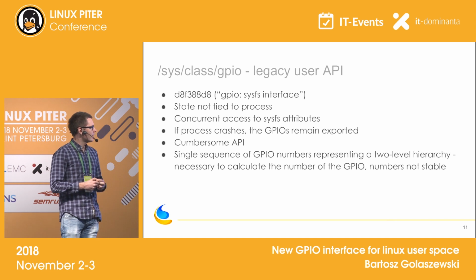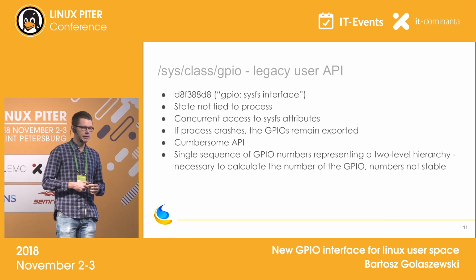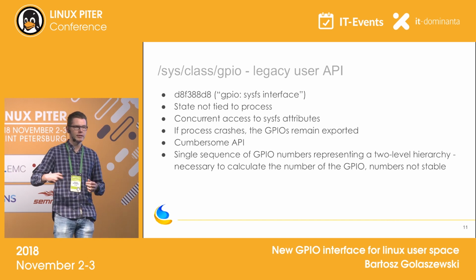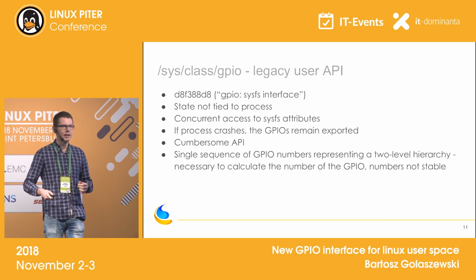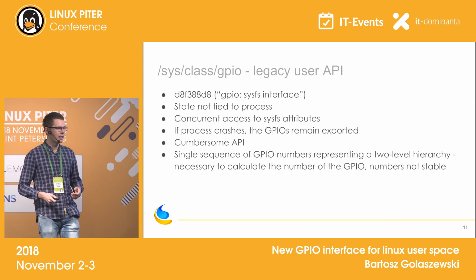So the problems are several. First, this is a global state that exists in sysfs, so it's not tied to any process. Let's imagine you have a process that does something to GPIOs, exports something, sets some values, and then dies or crashes. You never get back to default. This is going to stay like this.